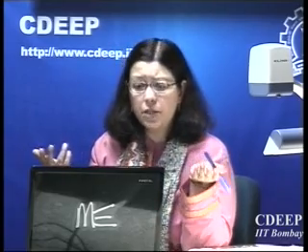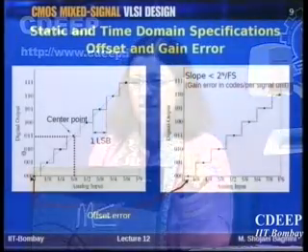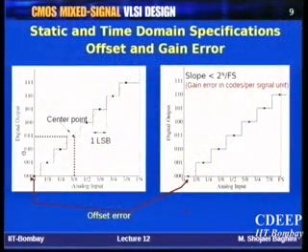So that's why inaccuracy is associated with the comparison, and inaccuracy associated with the reference level. Here we write the exact value of 1 upon 8. But it is not 1 upon 8, right? It is 1 upon 8 plus minus some delta. And that delta can be a very small value. But definitely it is not a femtovolt. It can be microvolt, it can be millivolt. So that leads to shifting these points in a real ADC.